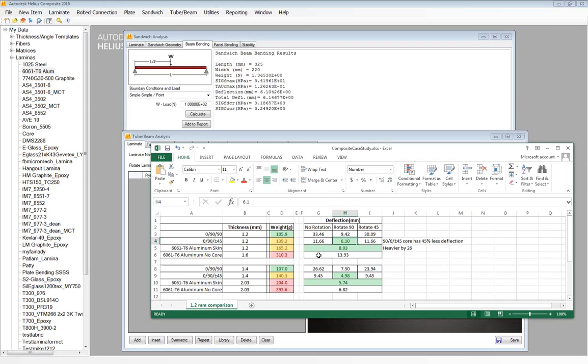Having a minimum amount of deflection in there prevents the panel from actually rubbing against any portions of the engine that might fray or wear through the panel, or the panel may actually fray and damage some of the lines, hydraulic lines or air lines, things like that. So there may be a requirement here. I was just looking at minimum deflections and just kind of doing a comparison of weight, so you can kind of see that for yourself.